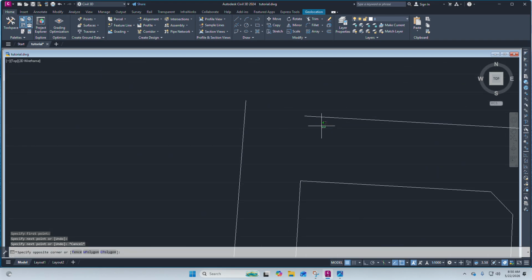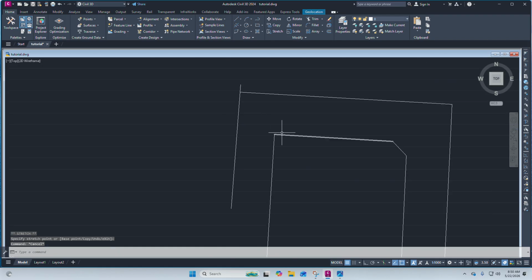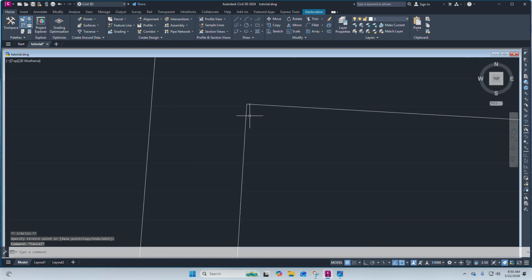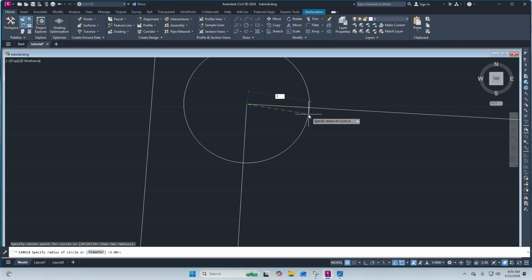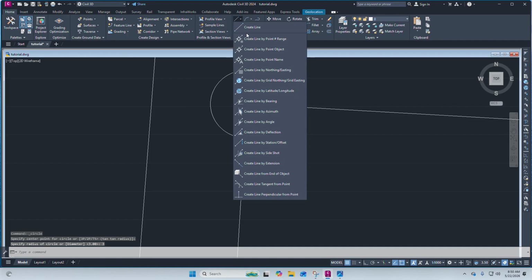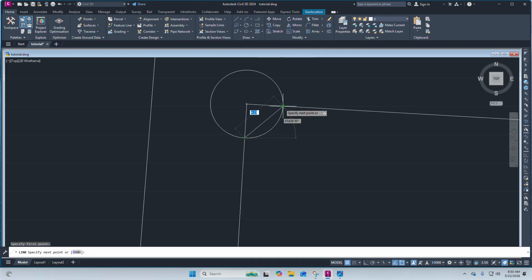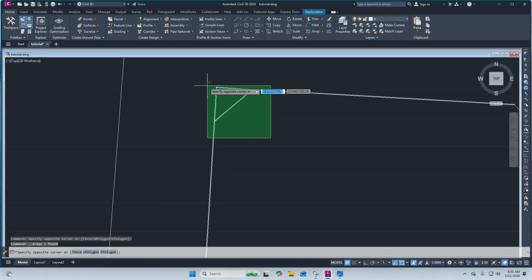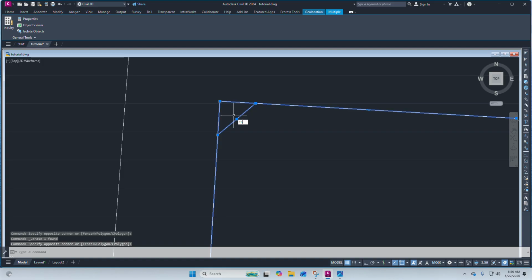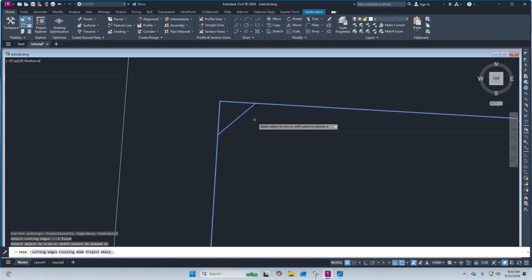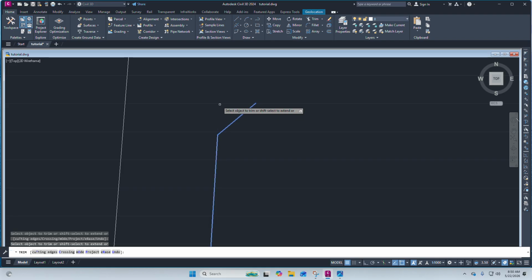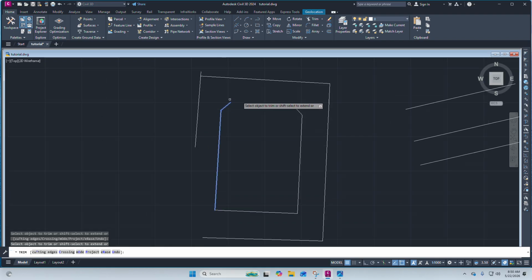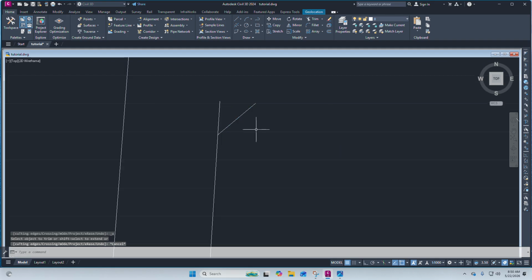Suppose you also have a line here. Let's just join them manually. So I would like us to do the truncation at this point. So select the circle, then 3 meters, hit enter, then draw a line from this point to the other, then do away with the circle, then highlight, then trim. From your keyboard, type trim, this line and the other one. So one disappears. I don't know why it is always disappearing.